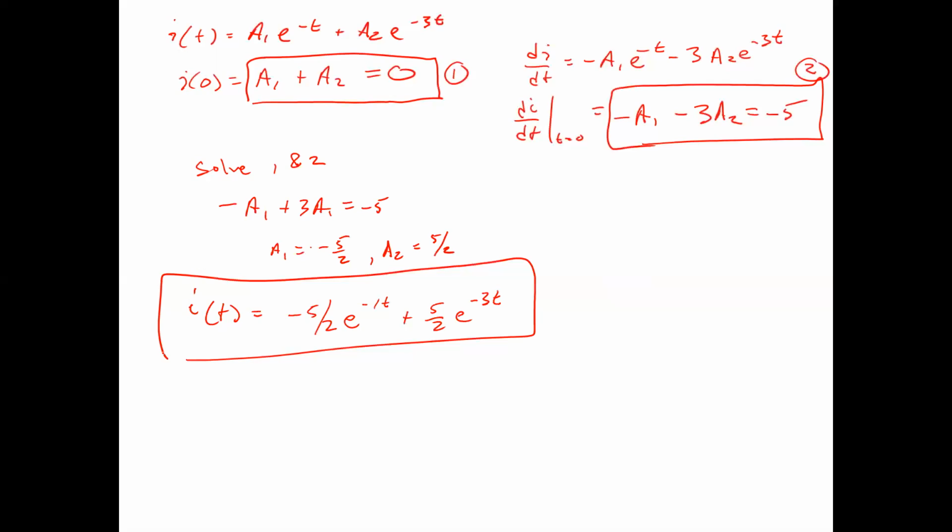Yeah, so Hong says because it's a second order circuit, you have 2 constants you got to figure out. 2 constants means you got to actually have 2 initial conditions. With first order circuits, all we need is 1 initial condition because that's all we need to line up the solution, right? But with second order circuits, it's unconstrained also in terms of the slope. Depending on the values of A1 and A2, you could actually have an initial slope that's completely different. So you need the slope to actually figure out exactly what A1 and A2 are. Isaac.